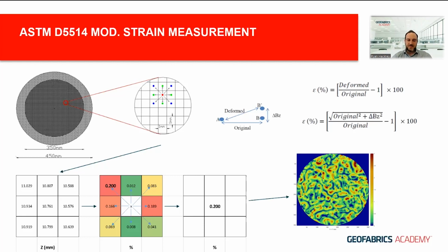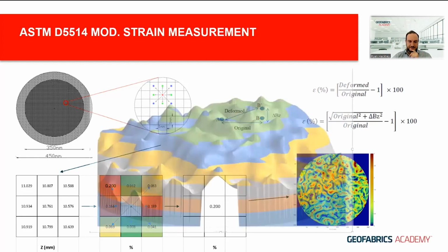Not every 3 millimeters like you see in the LFE2 method, not just 5 select indentations. Every single part of that plate is captured on a 1 millimeter resolution, and the strain is measured at every single point around it, not just x-axis and y-axis, every single point around it. So we get a really high resolution in terms of what the strain is.